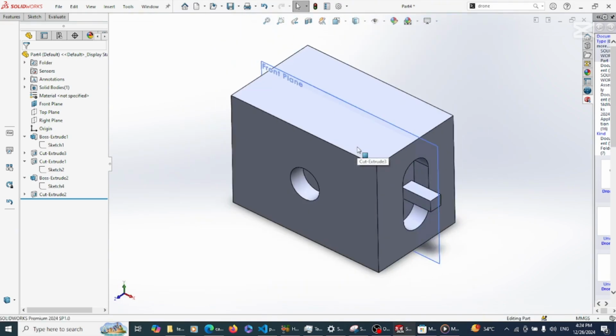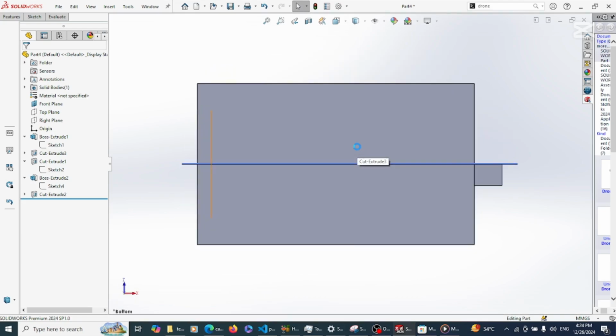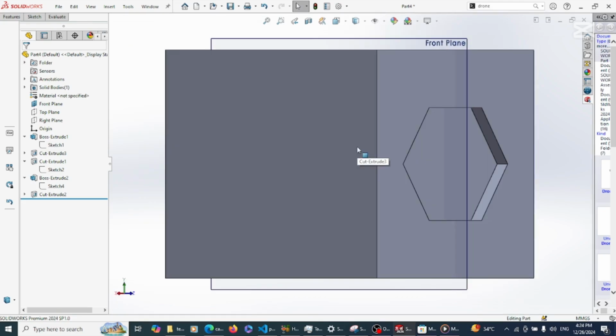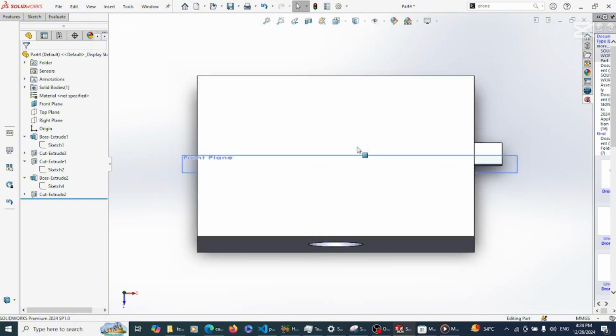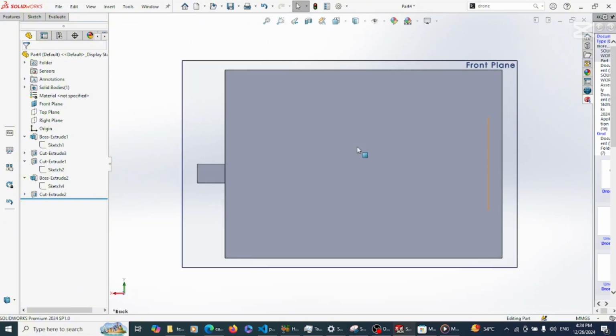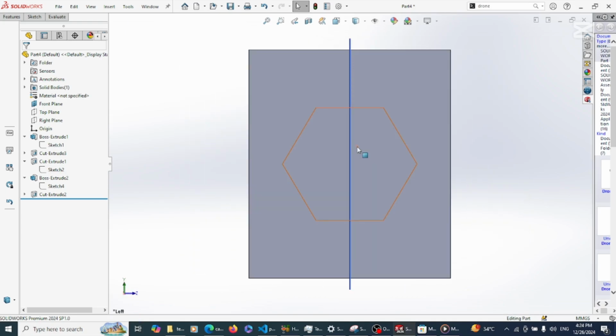So Control 7, Control 6, Control 5, just like that, to change different views for you, top, left. So you just find out. So Control 1 is what? Front. 2 is back, is front, but it flips it. 3 is what? Right, which is the left side. Follow my cursor, check this guy here is going to already show the side you are looking at it from.